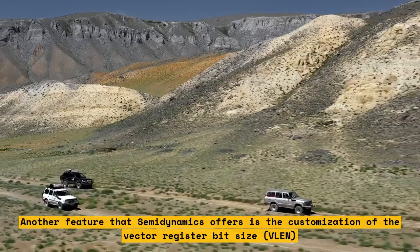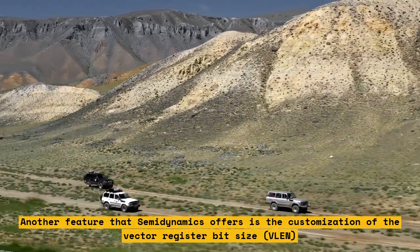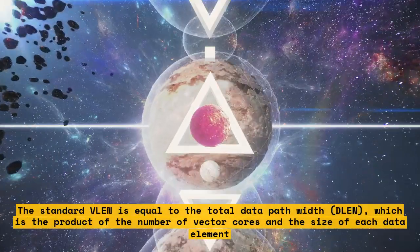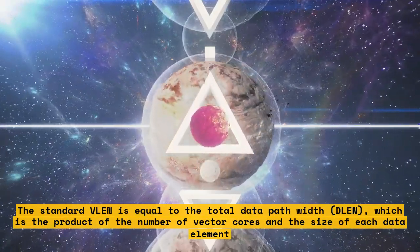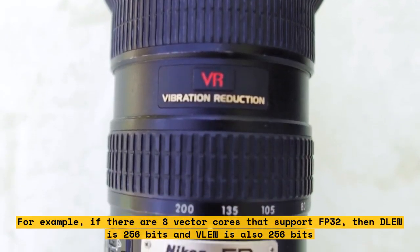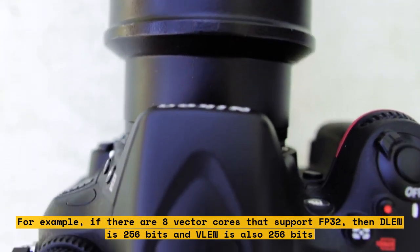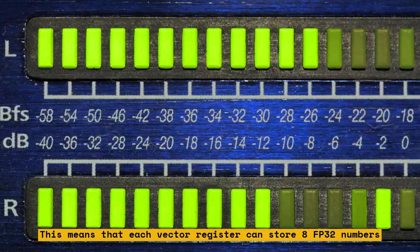Another feature that Semidynamics offers is the customization of the vector register bit size, VLEN. The VLEN determines how many data elements can be stored in a single vector register. The standard VLEN is equal to the total data path width, DLEN, which is the product of the number of vector cores and the size of each data element. For example, if there are 8 vector cores that support FP32, then DLEN is 256 bits, and VLEN is also 256 bits. This means that each vector register can store 8 FP32 numbers.